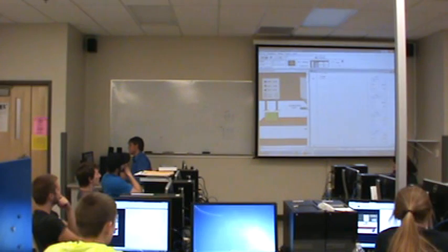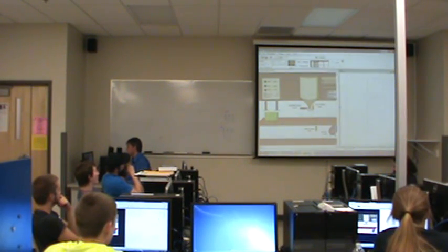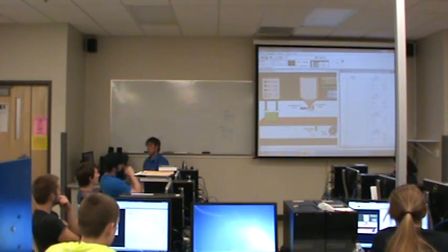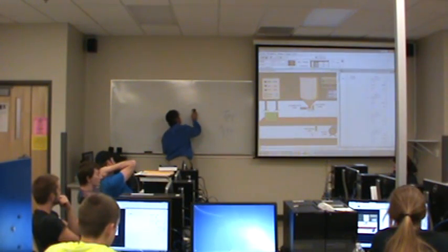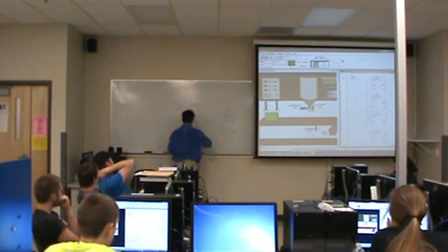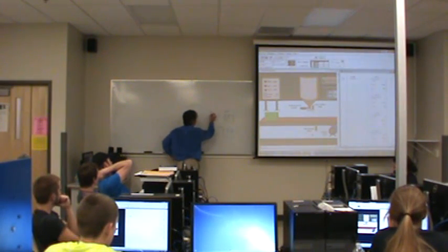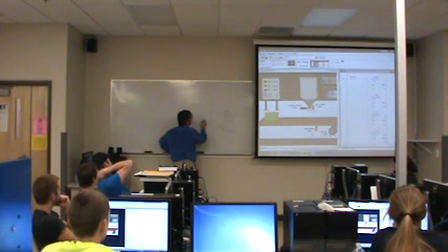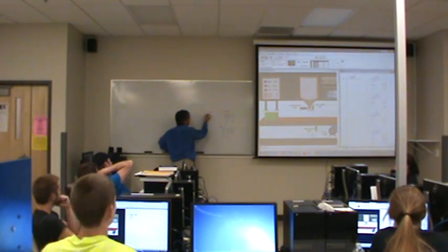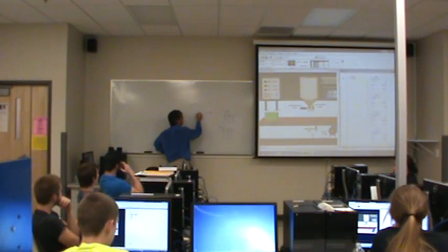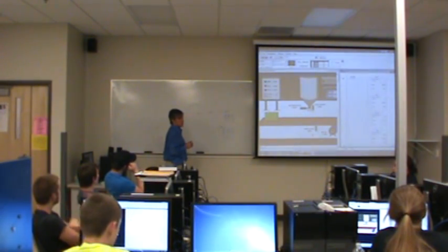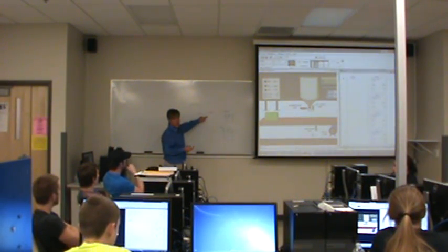Now, what bits do I really want to look at on the inputs? 3 and 4. So what should my mask look like? Consider that. I am not interested in bit 0. I'm not interested in bit 1. I'm not interested in bit 2. I am interested in bit 3. I'm interested in bit 4, and there are no other bits that I'm interested in. So that in binary should be my mask.